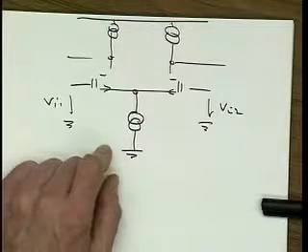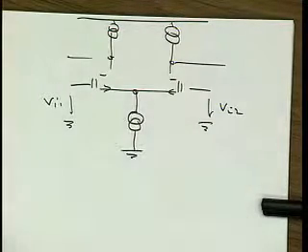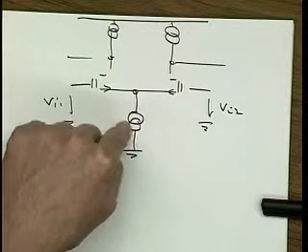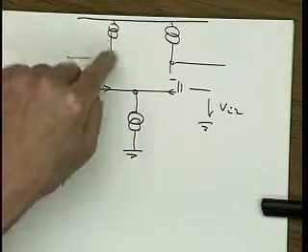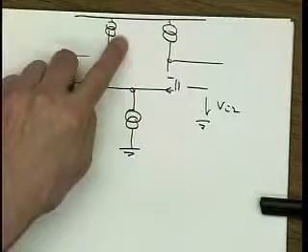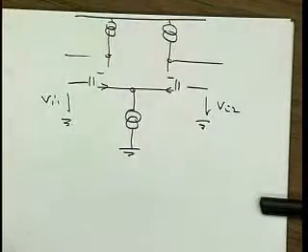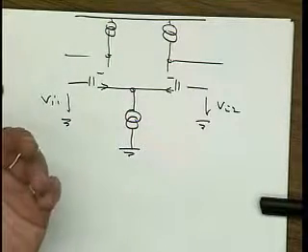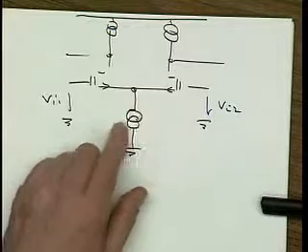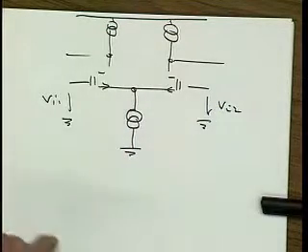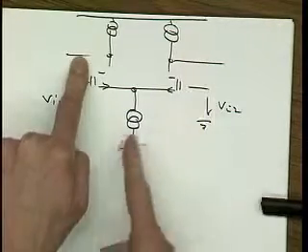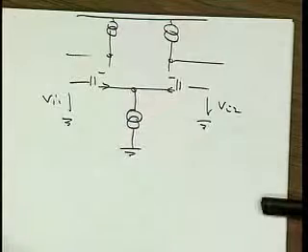And even though the common mode rejection ratio in practical circuits is usually not infinite, maybe 60 dB, this noise here is attenuated by a factor of 1,000. It starts out being roughly the same. These are both current sources, so they run similar current, so they produce about the same noise. But this one affects the circuit by a factor of 1,000 less. So in practice, most of the time, we can just neglect this. But be careful if you use the amplifier open loop. Then depending on the setting here, you're going to push the noise this way or that way, and the noise even becomes signal dependent. Careful.